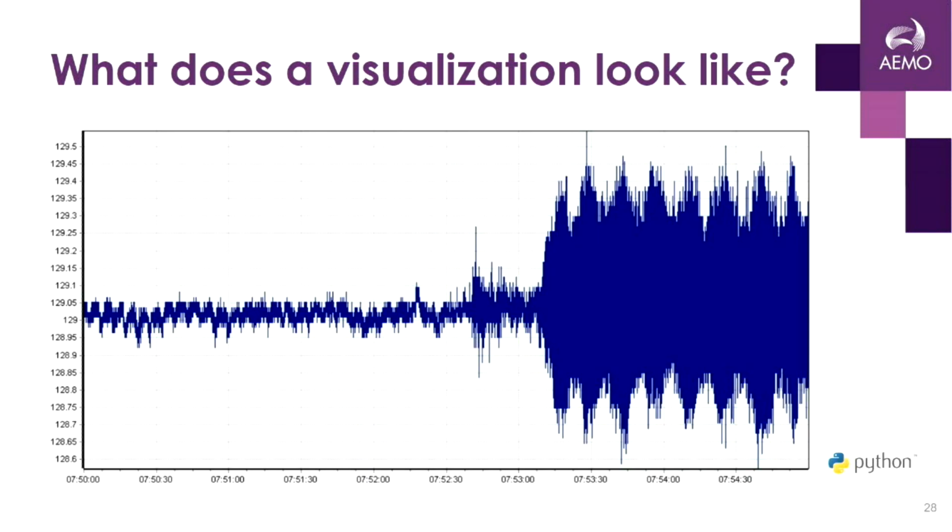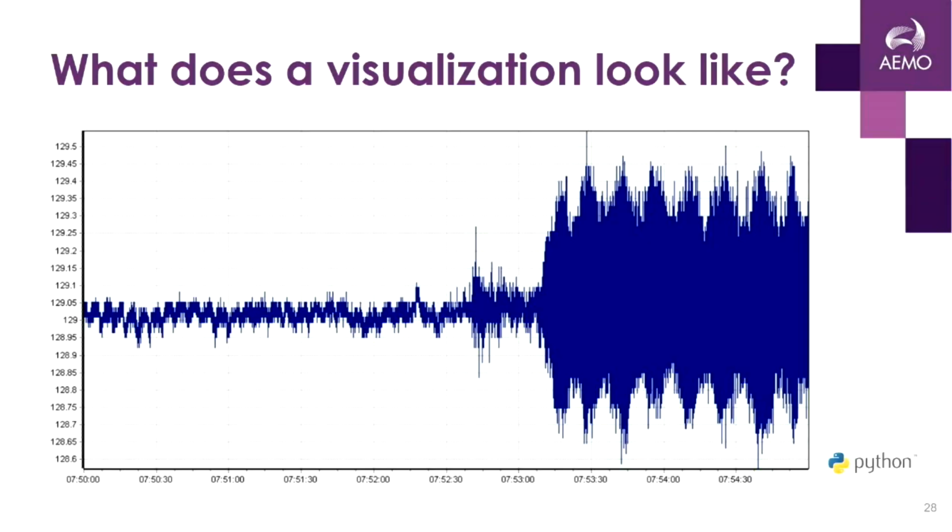This graph shows a trace coming out of northwestern Victoria. Northwestern Victoria has a very high penetration of grid-scale solar. Grid-scale solar does not bring that rotating mass I spoke about, so it's vulnerable to disturbance. We have a Python system that is watching the flow of data as it's ingested into AEMO, looking for oscillations like this. The tech is NumPy and SciPy performing a fast Fourier transformation, looking for changes to the shape of the sine wave.